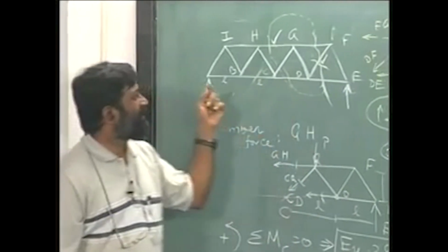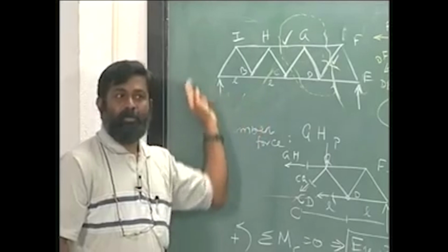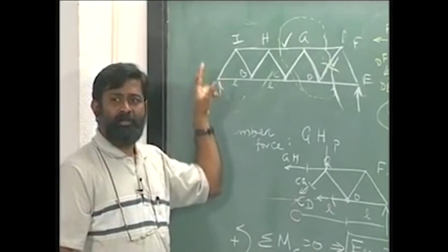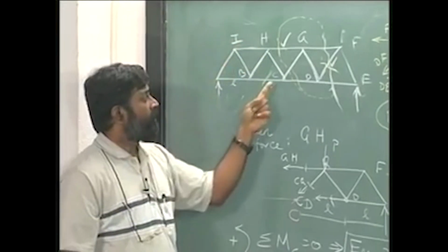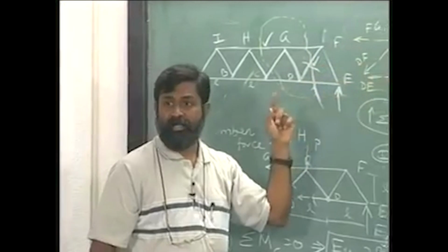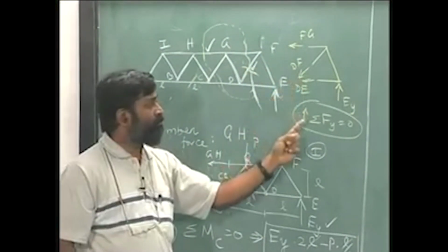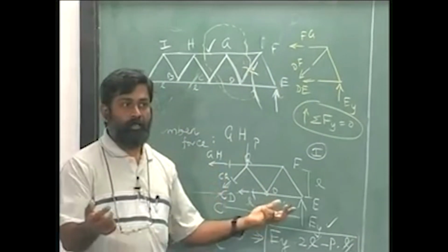So in short, you will find out an appropriate section, take a particular section which is simple, in which less number of forces are acting. If there are 3 forces like this acting and I want to find out one of the forces, then find out which equation will be the most appropriate to solve, and there you go.